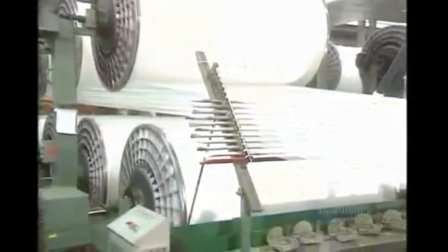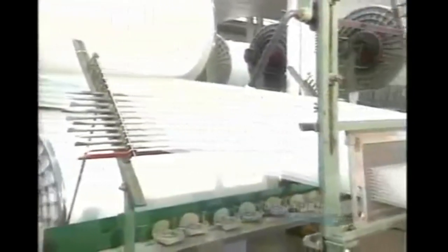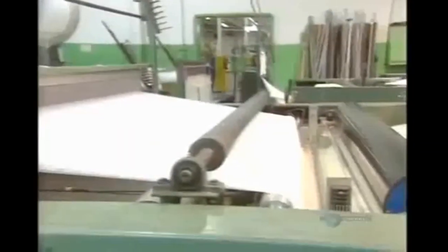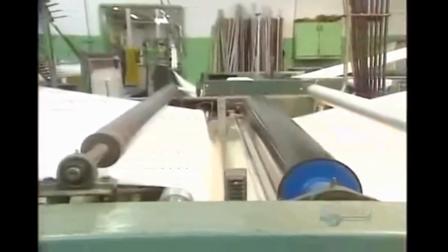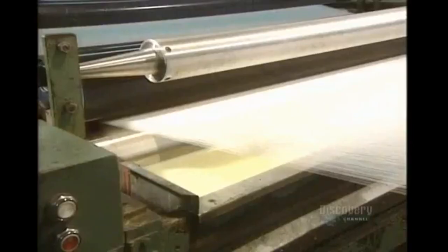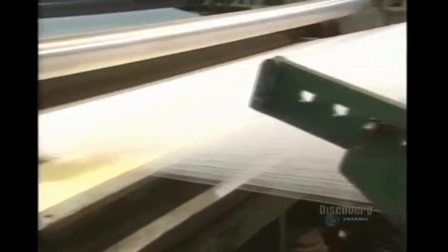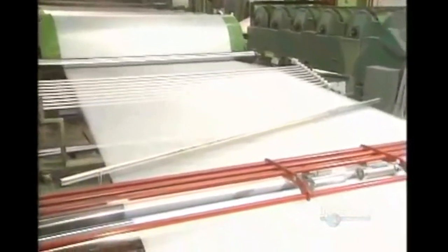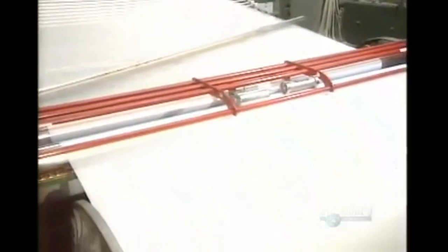One fabric is composed of threads braided at 90 degrees. The warp threads are assembled lengthwise, while the weft threads are joined transversely. To prevent the threads from tearing, they pass through a bin of glue. These rollers eliminate the surplus. The glue will be removed with water before dyeing the threads. The glued together threads exit this machine. These large green cylinders are heated and dry the glue on the threads.